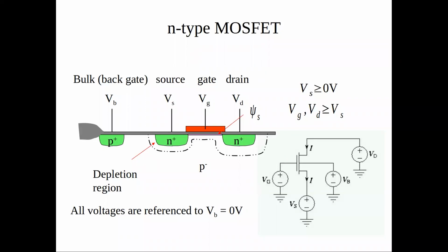Okay, here. We can then create an ohmic region between the substrate and then some terminal, which we can call bulk, the VB. And then we now have access to the reference voltage. We don't have to go from below the wafer. We have access to the reference voltage as a metal line together with all the other metal lines. And this, as I said, by default, is connected to ground. And all the reference voltage of N-type transistors is always ground.